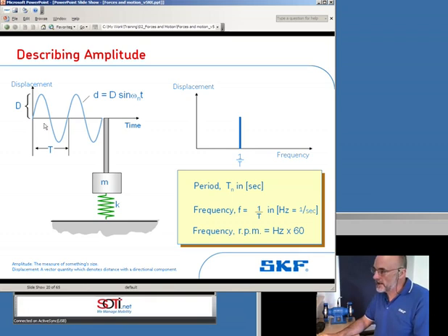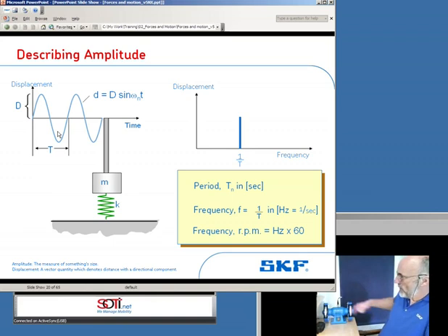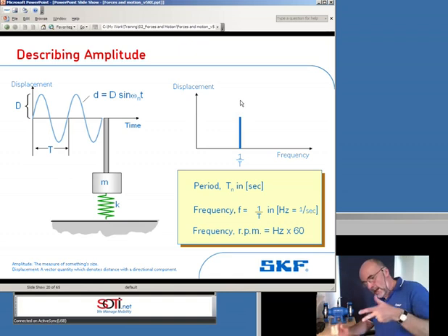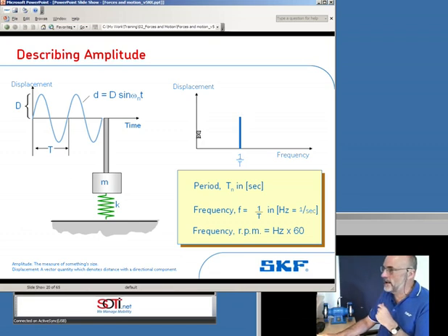We've got this sinusoidal signal going on, either from a pendulum or a rotating machine, and this machine is going up and down. And we're trying to tell you in an engineering report the size of that vibration. So on this thing called a frequency spectrum, we have frequency on the x-axis. On the y-axis, we have the signal that we're trying to measure, either displacement, velocity, or acceleration. And the height of this line that you see is proportional to the level of vibration that we're getting. Now, there's a slight problem here.